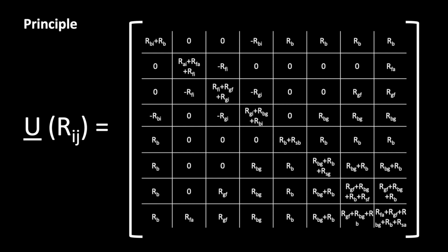The switches in our equivalent circuit diagram are also represented as resistors in our matrix. We find here the resistors for our 4 switches: RSB, RSG, RSF and RSA. If we want to simulate a closed switch, then we set the corresponding resistance to 0. For the open switch, we take a large value, like 1000 for instance. In this way, we simulate a switched on or a switched off heating.